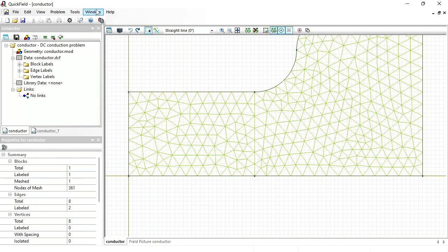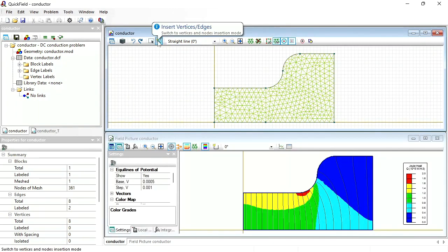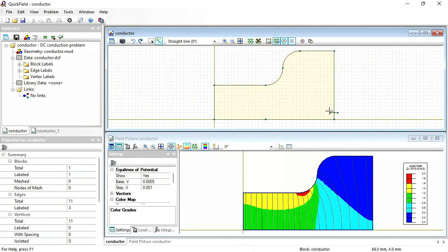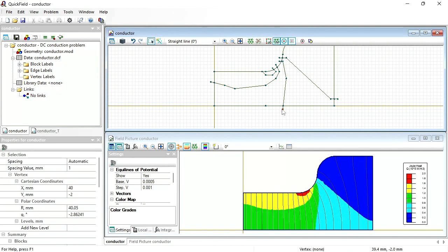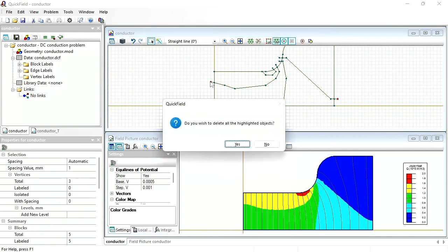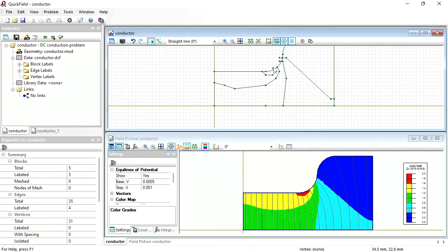Let's put them one above another, switch to insert mode, and draw the boundaries of the color zones, something like this. And this. And here. And the red zone is here. Okay, switch to select objects mode, select and remove unnecessary parts. Next, I'm going to run the simulation again to see how my artificial boundaries match the color boundaries.